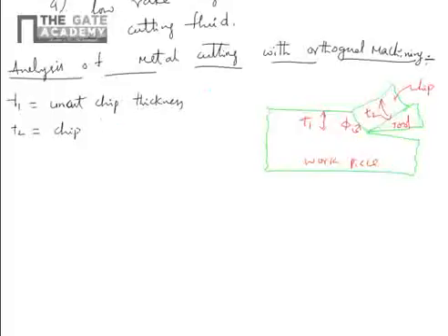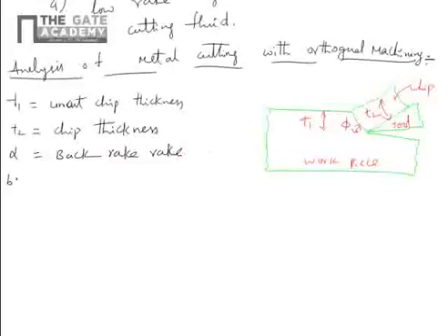This is the most important. If you have to remember this chip thickness and uncut chip thickness. Alpha is always back rake angle. Even if they mention rake angle, that is called back rake angle. Width: B1 equal to B2 equal to B equal to width of the chip. So the width assumption is that the width of the chip remains constant always.